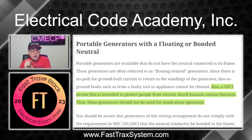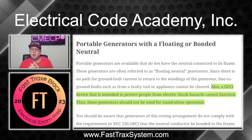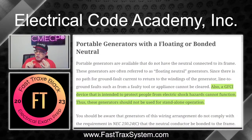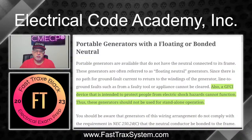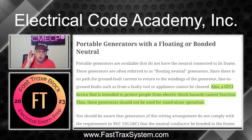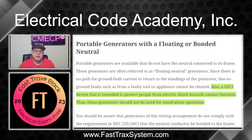So, floating generators that do not have a bonded neutral to the frame, you do not want to use on a job site, construction site, maybe for your camper or something like that. You don't want to use them in those applications. Okay, if you're relying on that overcurrent device on that generator, if you're relying on that GFCI device to function properly, you do not want to use a floating neutral generator. You want a bonded neutral generator.